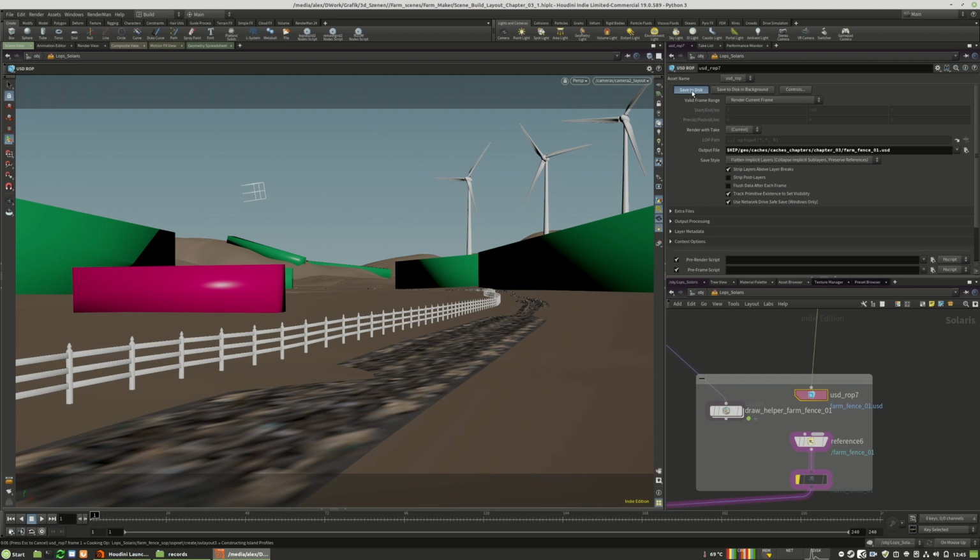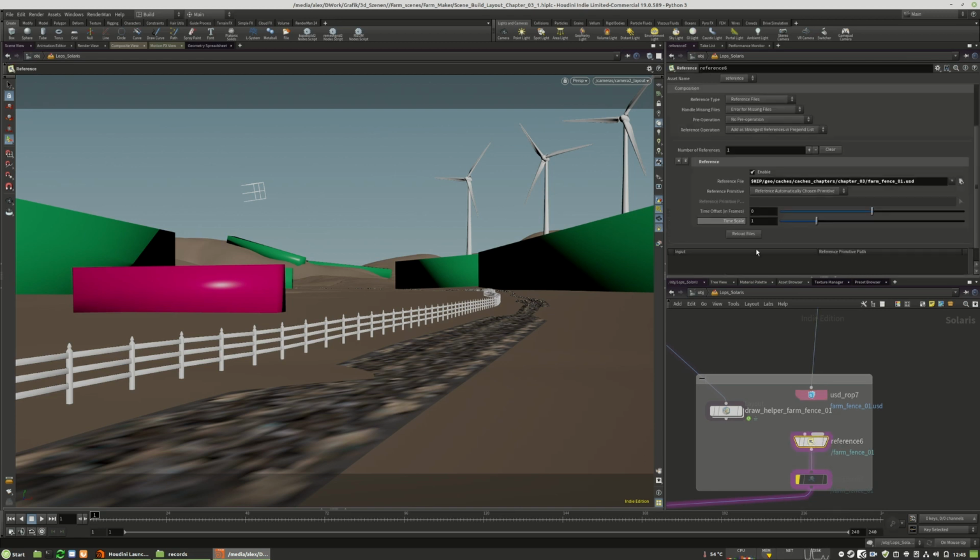So when you work in LOPs, make sure you use that update toggle button on the right bottom side as much as you can. So when you know there is a node which takes quite a while to bake and you only need to change some values, turn to manual mode. It will save you a lot of time as well as crashing.